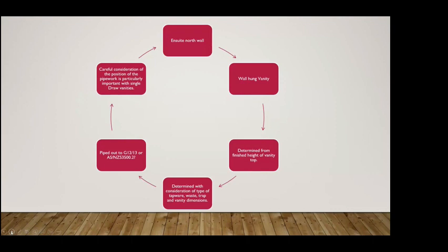And if it's leaking a little bit, you can't leave it and pretend it didn't happen. It's only going to get worse eventually, and people are going to notice it. So you've got to do what you've got to do to get it right. Sometimes that might mean you've got to bite the bullet and cut some tiles out, get back into it a bit, and try to do it ideally without affecting the finished thing. But if it's really bad, there may be no option but to pull the wall off and have another go at it.